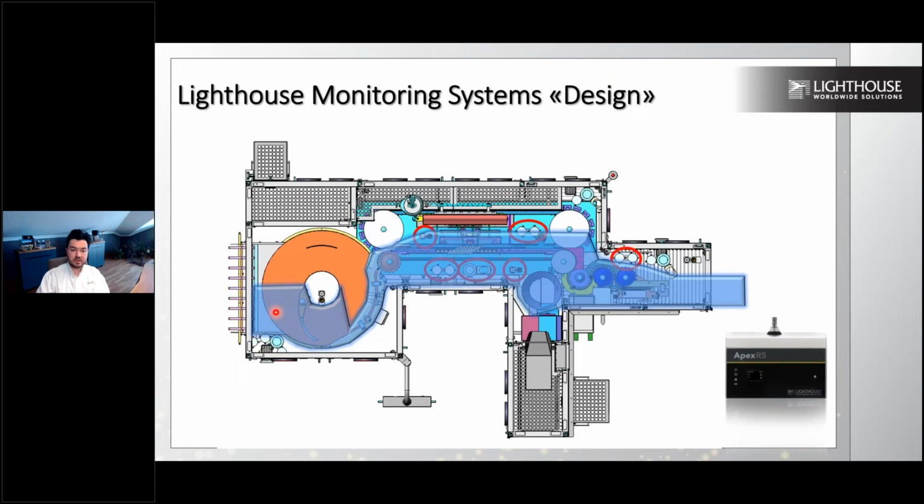The reason I'm saying this is because we know that the turntable is turning counterclockwise, so that it collects all the samples and allocates them directly into this line, so that they go one by one into the filling needle. So the other side of this turntable, for example, is not as critical as the side that we are dealing with. The reason is that all the operator interventions, all the gloves are on this side for this RABS system. So we know that the process will be maintained from this side of the operation,